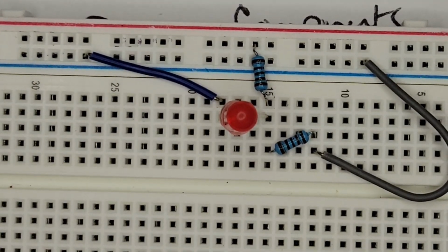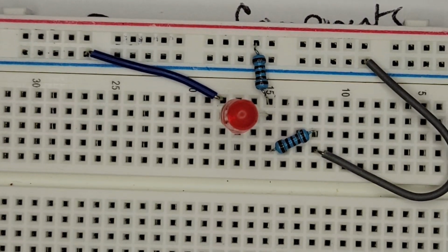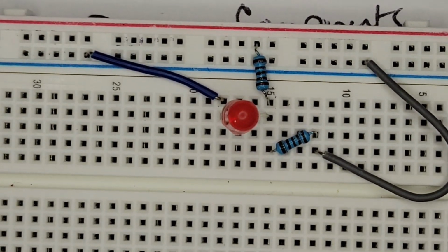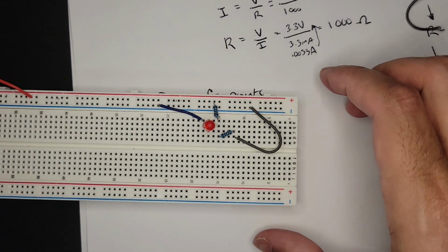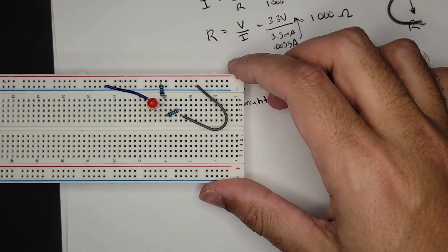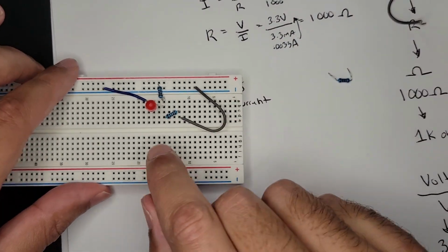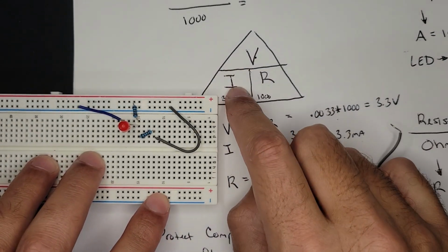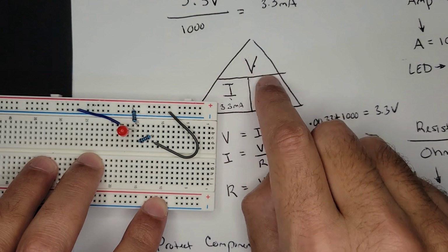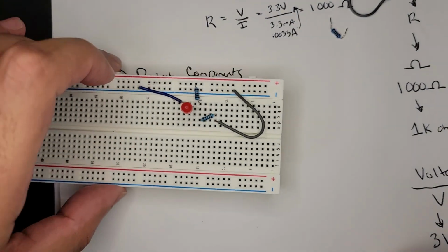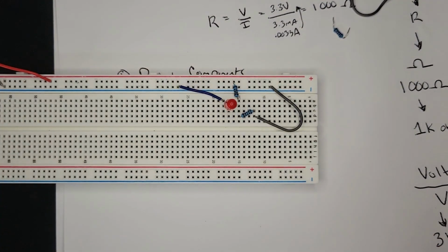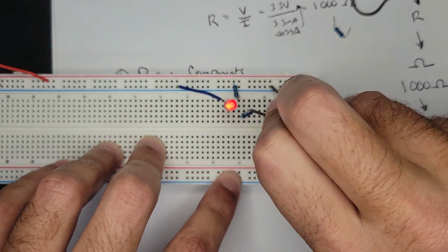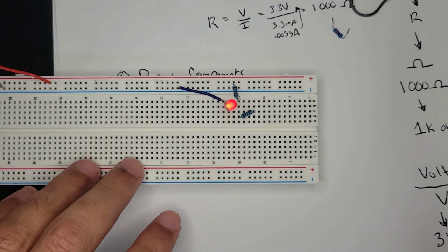There was something else that I wanted to do here. Let's start taking some voltage readings. And we could break it open again and keep taking current readings, but we already know that we can figure out our current by just dividing the voltage over the resistance. So let's do another test. I'm going to unplug our alternate path to ground, which turns on our LED.